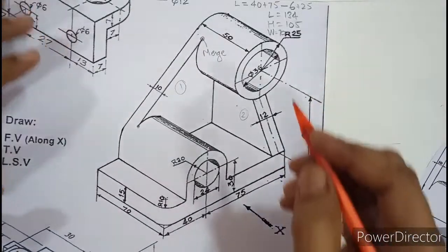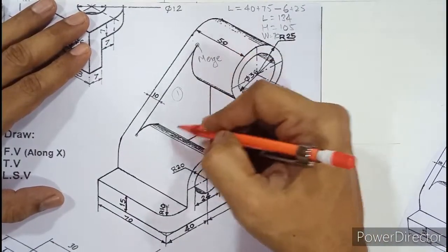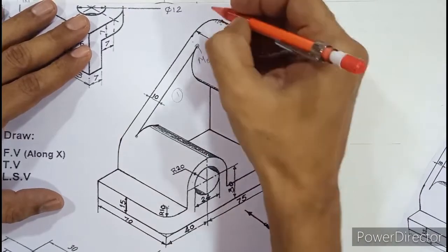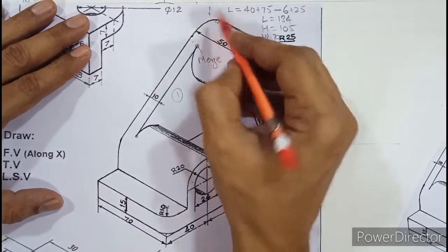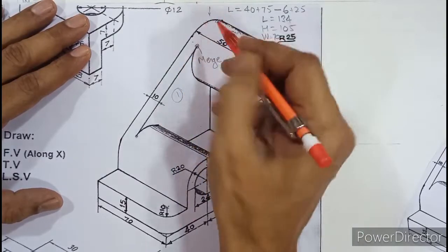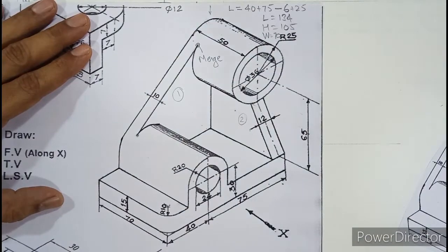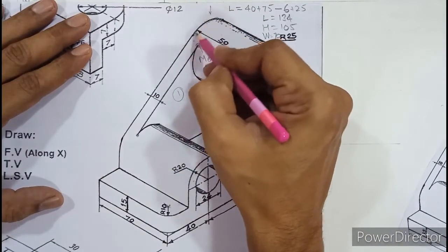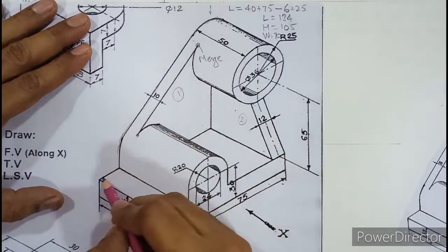I need to make you understand one new important thing: whenever you feel that the top view is complex, how to start with the top view and draw step by step. So look in the top view and try to visualize the rear edge. See, look at this line that I'm marking. Look at this rear edge carefully. So when you look at the rear edge, look at it all together. Try to visualize this edge together from here down till here.